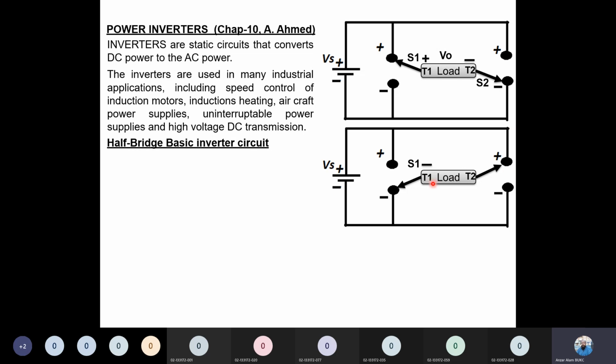In this circuit, if you connect your load, this terminal of the load is now connected with the minus, and this second terminal of the load is connected with the positive. So the voltage at this load will be plus minus with respect to this point T1. When we talk about voltage, we always take a reference, and this time the reference is T1. In some books, it is written as A and B, load 1 or load 2.